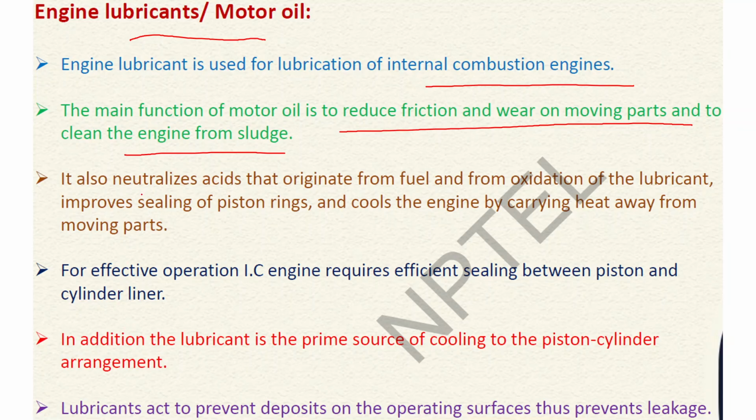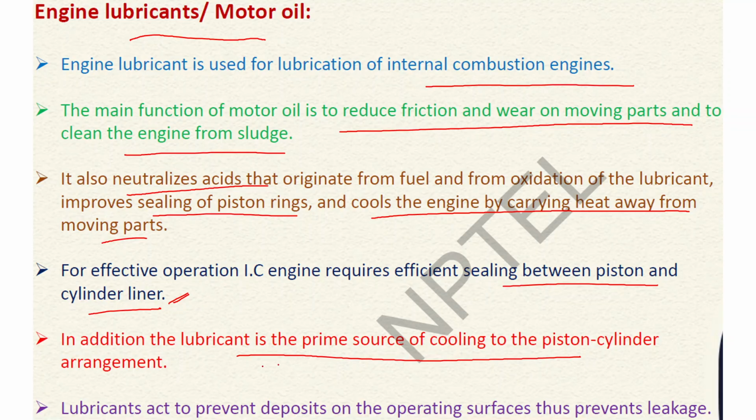Therefore, this motor oil also neutralizes this acid that originates from the fuel and from oxidation of the lubricant, and it also improves the sealing of piston rings and cools the engine by carrying heat away from the moving parts. Effective operation of an IC engine requires efficient sealing between the piston and cylinder liner, and this motor oil helps with that. In addition, the lubricant is the prime source of cooling of the piston cylinder arrangement. It also acts to prevent deposits on the operating surfaces, thus preventing leakage.